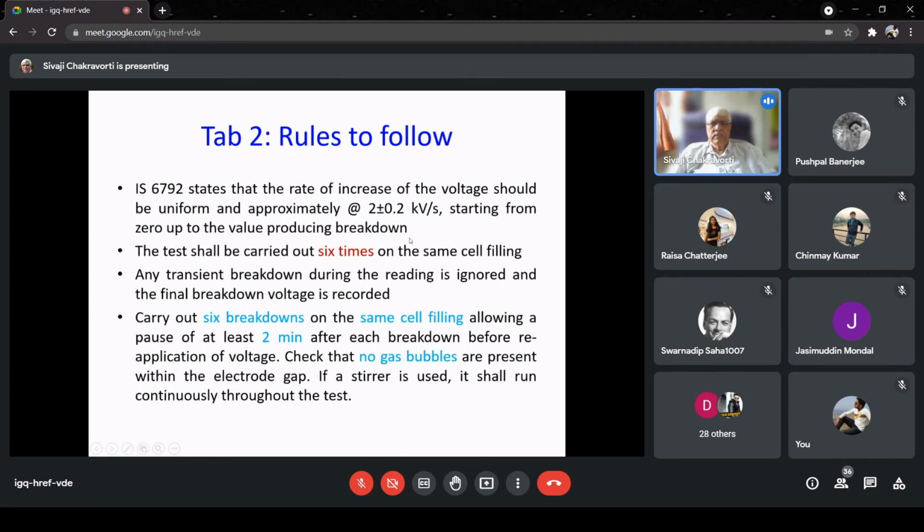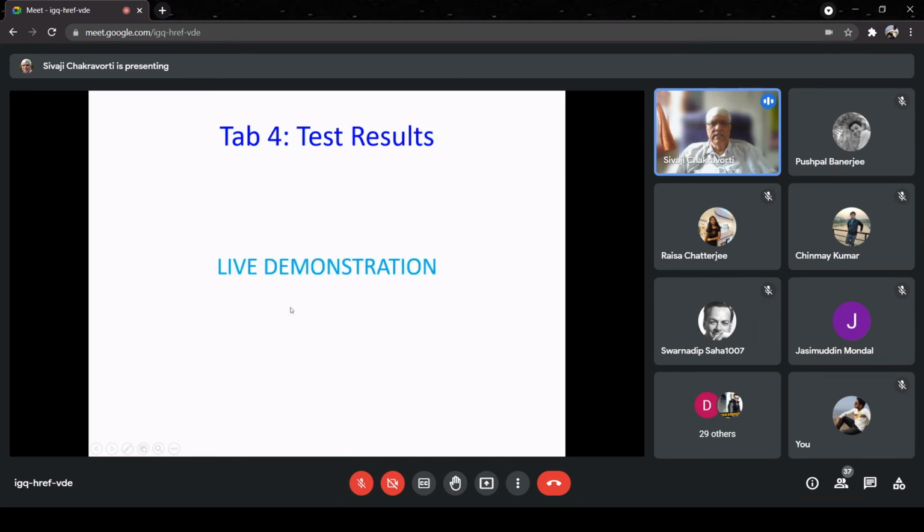The next question you can ask me, how many times do I do the test? The answer is, IS says 6 times. And a third point is already stated: the transient breakdown, if it happens, please ignore, only the final breakdown is recorded. And when we do a breakdown test, once a breakdown occurs, we cannot test immediately again. We have to give a pause of at least 2 minutes. We have to find out whether any gas bubble has been produced due to that breakdown. If it is there, a glass stirrer is used. With the help of the glass stirrer, we remove all the gas bubbles, and then after 2 minutes, we can do the second run.